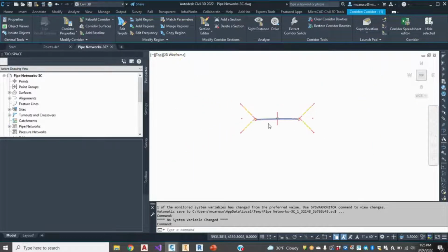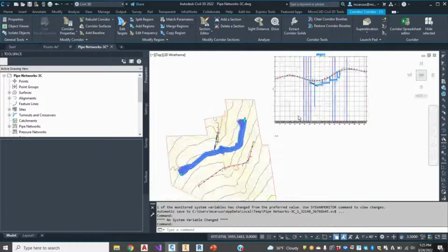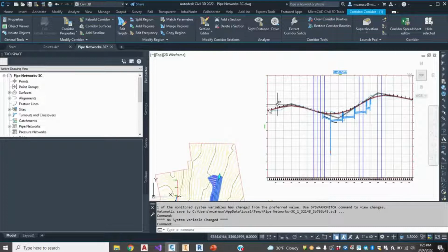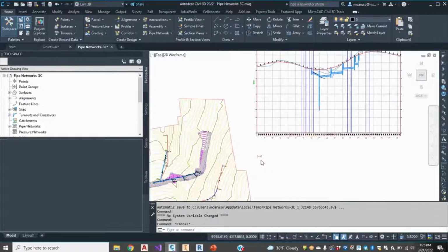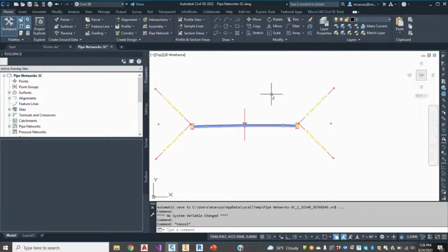And so that creates our wireframe roadway model, and it's got a horizontal control along the alignment, and it also follows a profile for vertical control. So the assembly is made up of individual pieces like lanes and shoulders and curbs, and sometimes our library of assemblies doesn't have what you may need. So for instance, maybe we are after the curb, maybe there's a sidewalk, and then some type of stone wall after that. So we can draw the cross-section of any shape with a polyline and then convert it into a